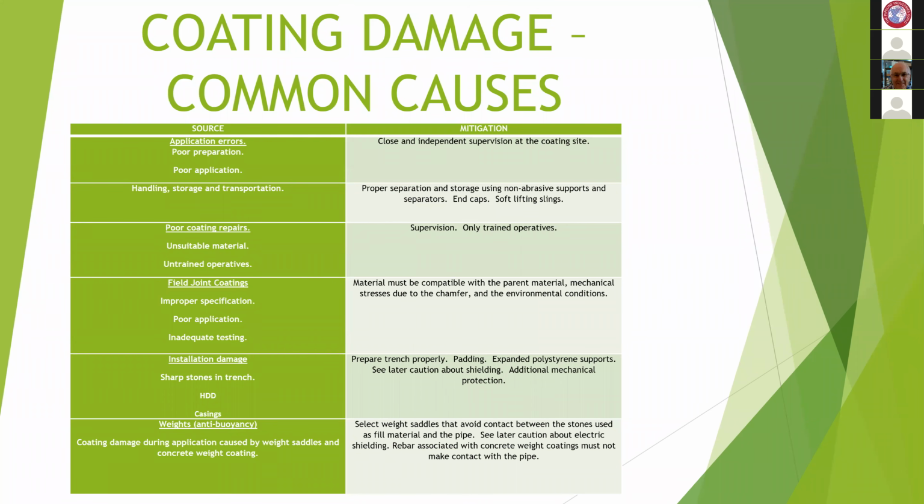And in areas where there is coating damage and it coincides with AC interference or DC interference, our risks spiral. They become huge, because we talk about 1 amp DC for 1 year consuming 9.1 kilos.